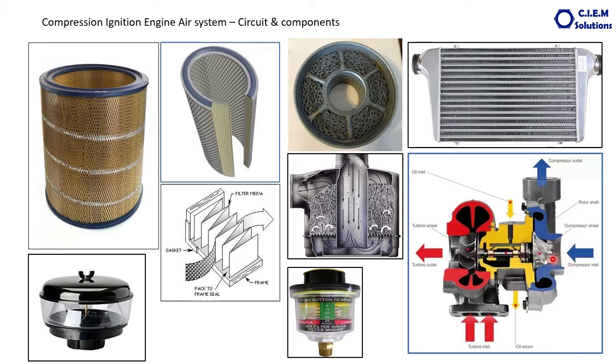The compressor wheel blades or vanes are in the opposite direction to the turbine wheel. So when the turbine rotates, it makes the compressor also rotate, allowing the atmospheric air to be pulled inside the compressor wheel housing. The air is pulled from the atmosphere inside the compressor wheel housing and pushed outside. This is the turbocharger. Turbocharger purely functions with the energy of the exhaust gases.